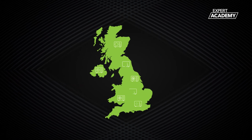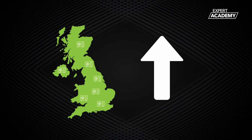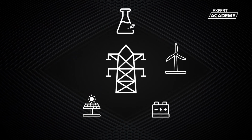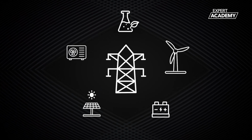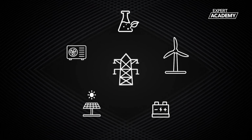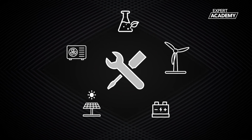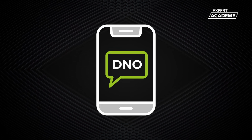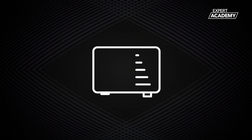As heat pump technology becomes more popular, the demand on the network rises accordingly. Furthermore, notifying the DNO allows them to monitor renewable energy installations across their network and anticipate potential upgrades and maintenance. Therefore, the notification or application to the DNO is a mandatory step in the heat pump installation process.